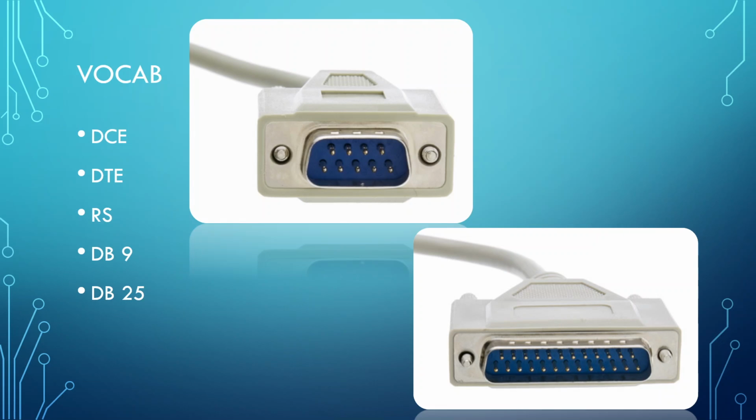Up on the screen right now, I've got the standard serial connections that you guys are on. The most standard one is this one at the top right. This is a DB9 connector. If you turn this picture onto its side, the middle shell looks a little bit like a D, and then there are 9 pins in it. So that's where DB9 comes from. That is, as I said, probably the most standard serial connector you're going to see. The one at the bottom, I think it's a DB25, if I remember correctly. It's out there, not quite as common.